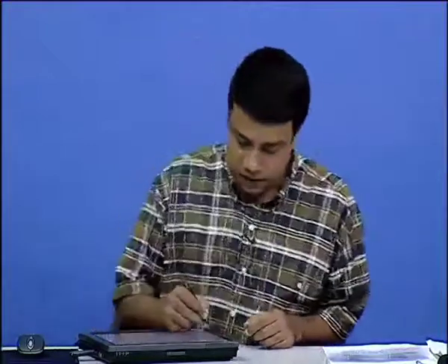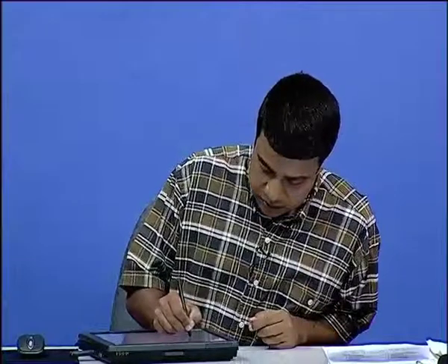Where the turbulent viscosity is modeled as rho times a constant times the kinetic energy square divided by the rate of dissipation of energy. The kinetic energy goes as length square per time square and the dissipation of energy goes as length square per time cubed, and you can see that this combination basically gives you velocity times the length scale.